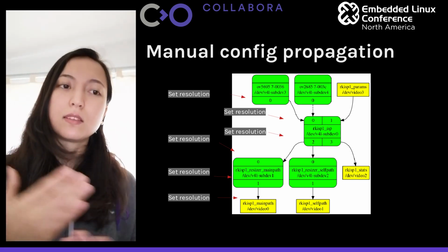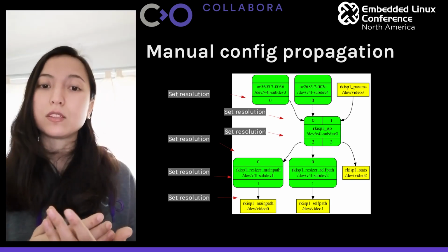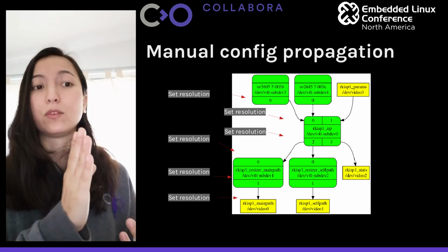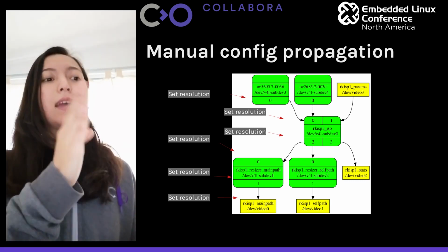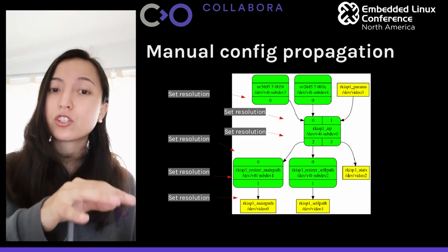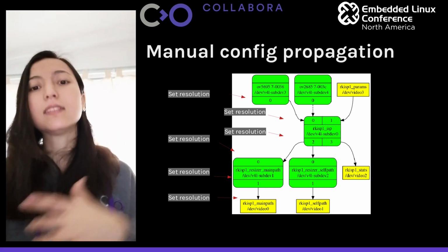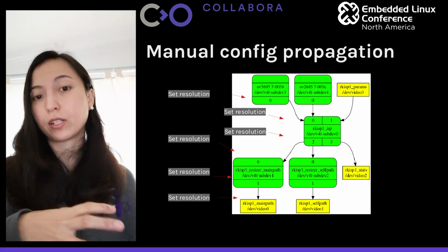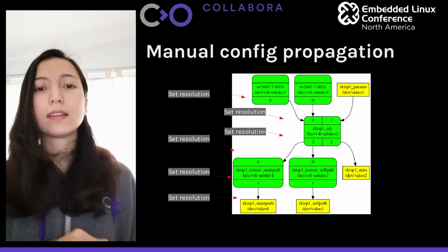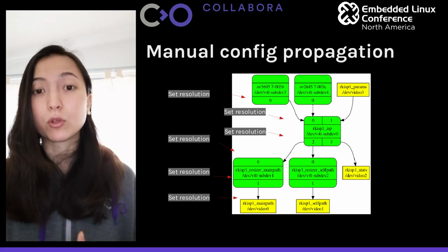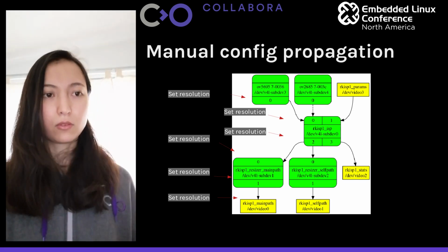Then user space needs to configure the resolution that the ISP needs to generate, and it needs to match the resolution that the resizer expects, and needs to configure the resolution that the resizer should generate, so it could be bigger or smaller to zoom or shrink the image, and finally setting the resolution that is expected inside the memory buffer for the final image.